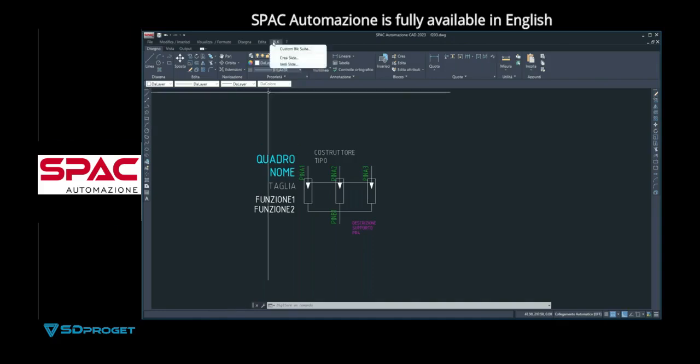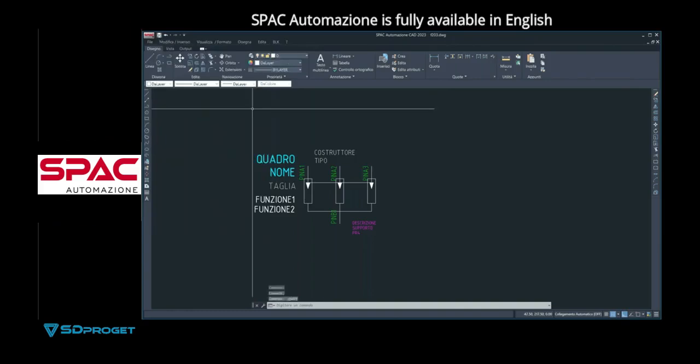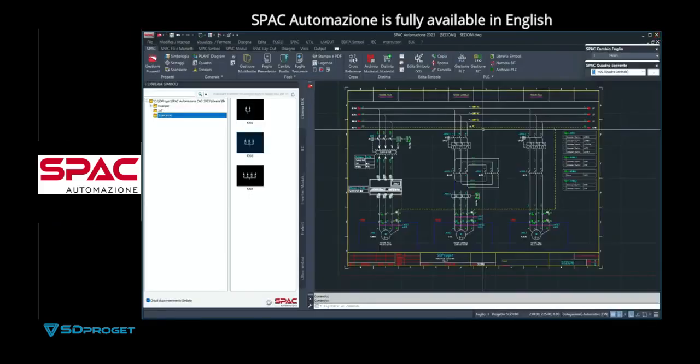Once that operation is done, I can also go and do create slide. The slide is the preview I see when I have the block list. Okay, view slide is the command you need to see the slide that I made. So once everything is over, I'm going to save my block and close it. So if I had this block here already drawn, then I would also have to do the slide with the little line above it.